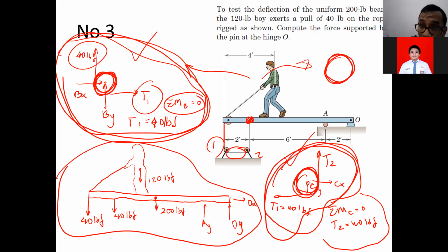If you draw just the pulley and separate it from the rest, then what we will have is there will be tension force here, T, and tension here, T, and there will be reactions, something like Dy, Dx. But remember, this one is part of the internal force. If you want to separate that pulley from the system, then this is what will come out. Okay.